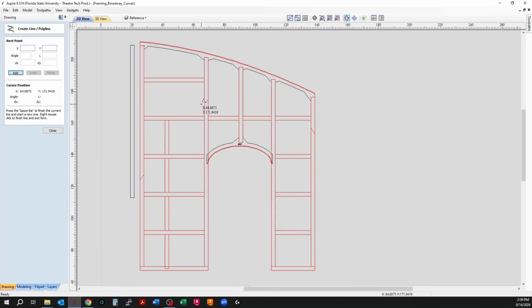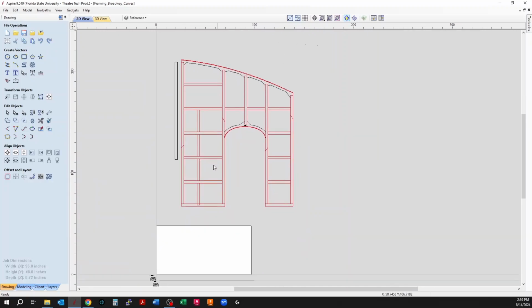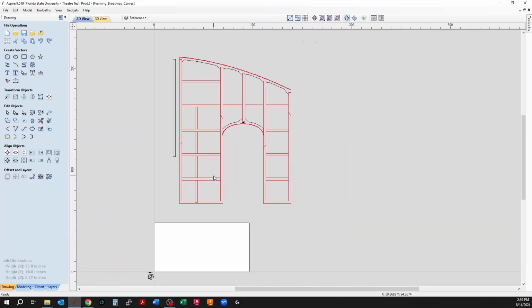It looks like these I'll also need some kind of seam break. Again, maybe over here, space bar to continue the command, somewhere over here maybe. And you can check those lengths and make sure that those work out for you, because you do need to be able to splice those pieces together. So finally, we're going to put our CNC'd components into our layout space. So this was just for that purpose of making sure we had 8-foot lengths.